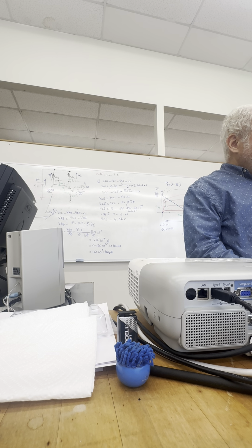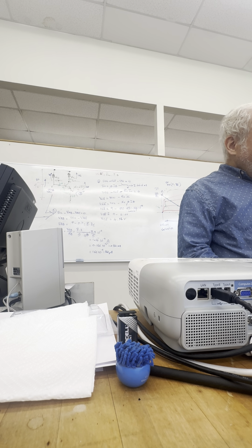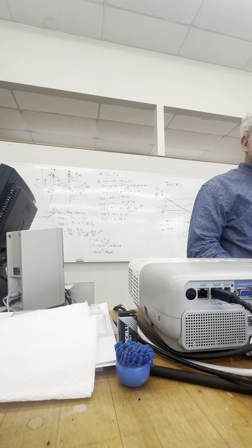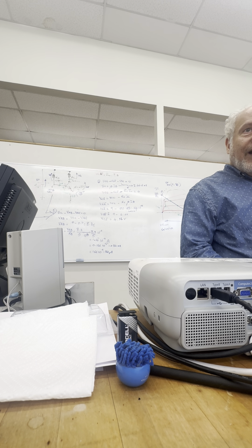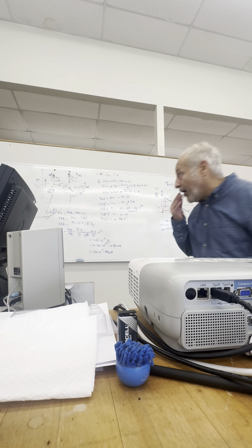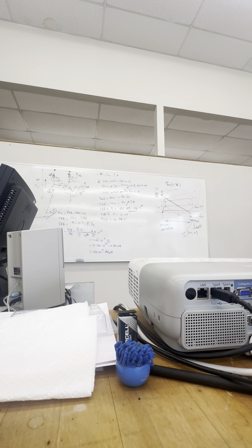And if I want to throttle the motor back down, I'm going to move my point from saturation to almost cutoff to shut it down. Well, I'm going to be controlling with RB because I can control IB. You with me so far?